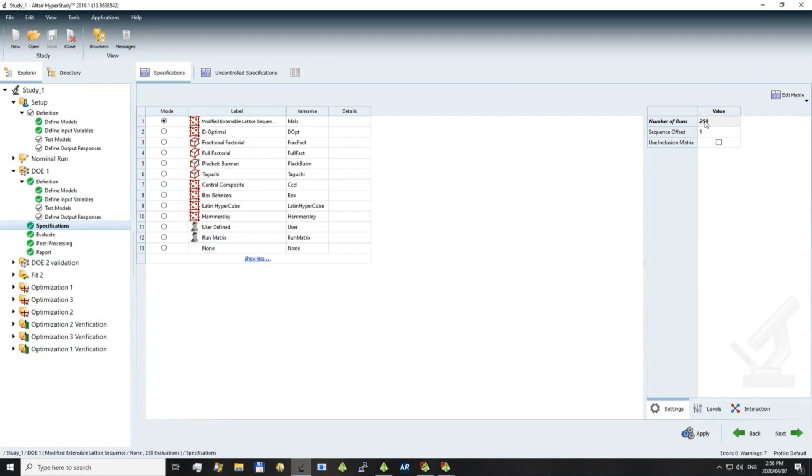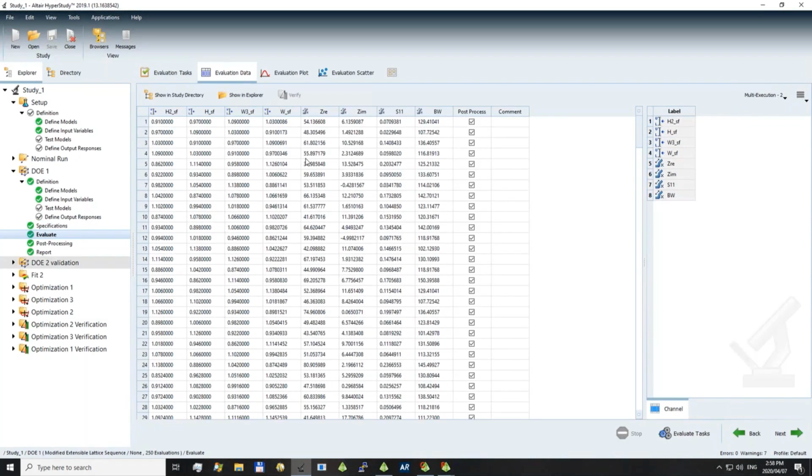So yeah, literally the only value that you need to set here is to decide how many runs to run, and it's a little bit complicated depending on the complexity and the behavior of the antenna in the design space, and also obviously the number of variables. So in this case, we ran 250. After you've run the simulations, you get a table, so you can see these are the geometric variations, and these are the results of all those parameters.